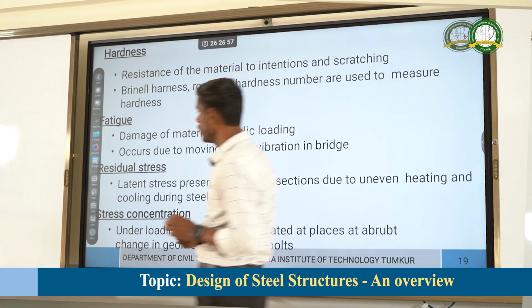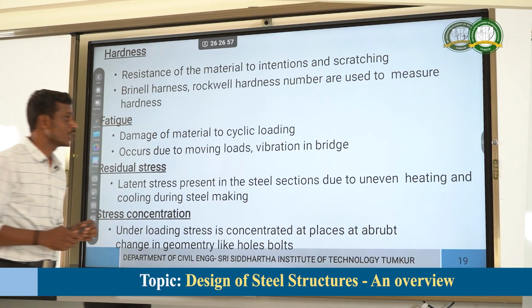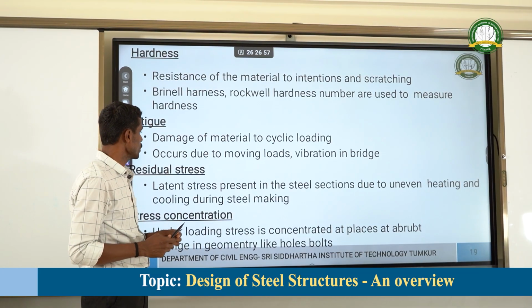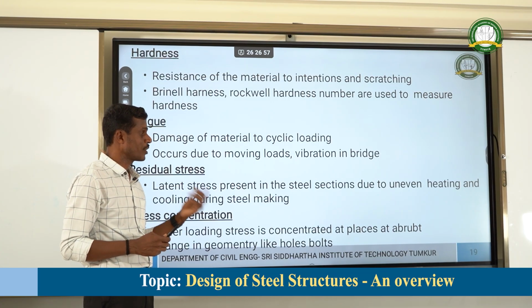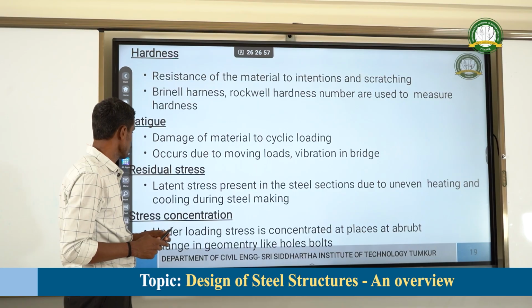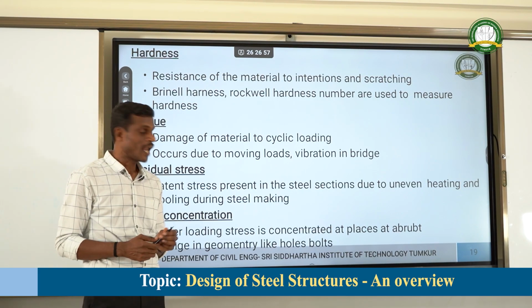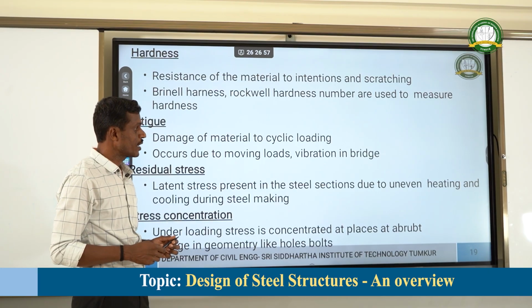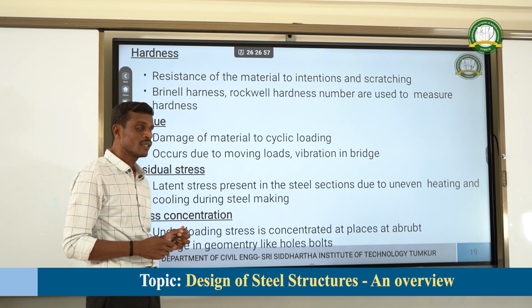Coming to fatigue, it is damage of the material due to cyclic loading. Due to the cyclic loading, it may undergo damage, which occurs due to moving loads and vibration on structures, it might be a building or a bridge. Then residual stresses are latent stresses present in structural steel, due to uneven heating and cooling during steel making.